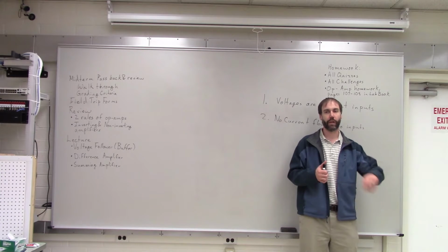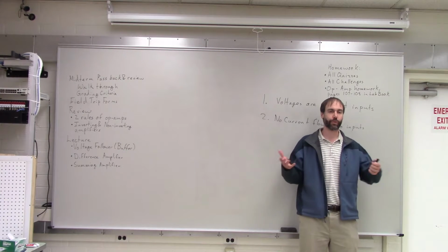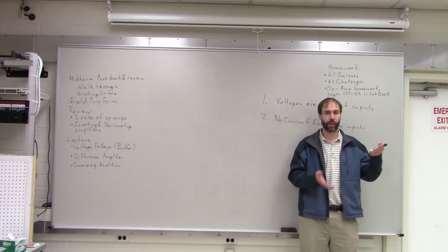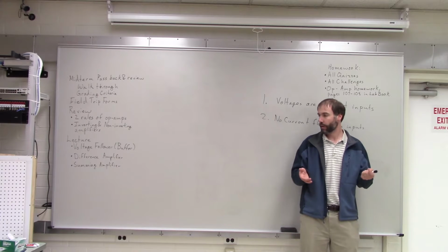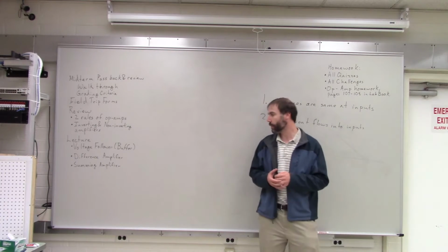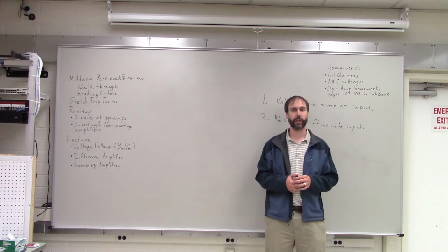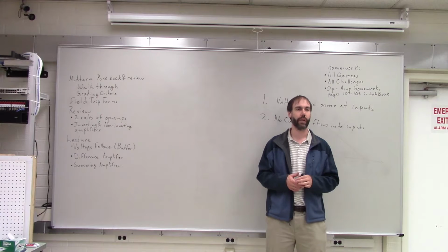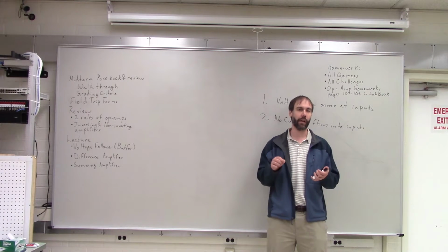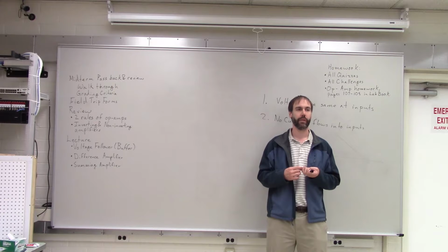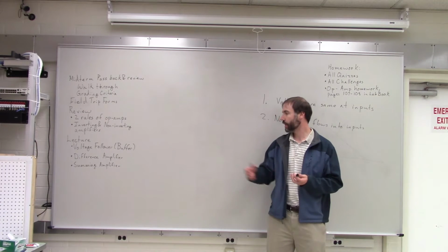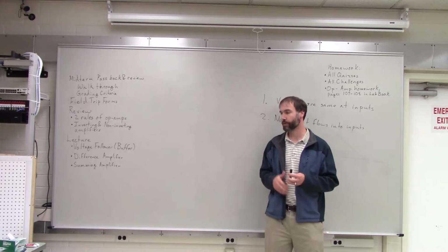You've got several different musical tracks that you want to combine. Maybe you want one to be louder and the other one to be a little bit softer. You would use a summing amplifier for something like that. Okay, so you would feed each track to a different input, and then you could adjust the gain for each track. You could adjust the gain for the entire combination of tracks, and then the output would be the sum of all those different inputs.